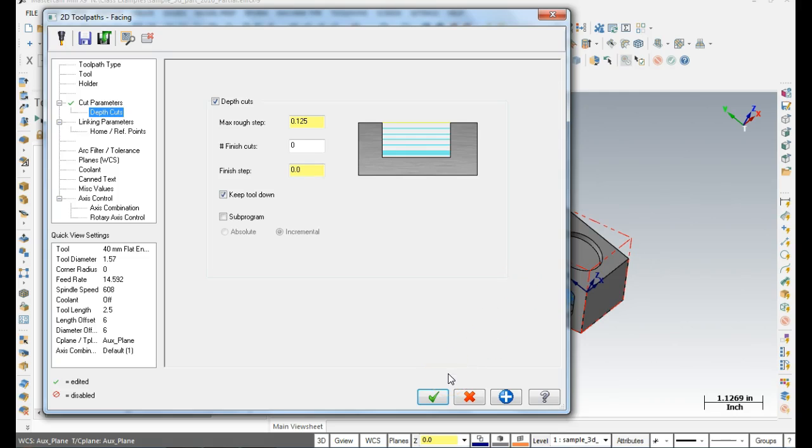Well, we have to have the face when we set it up, because we don't have a 5-axis machine. When we set it up, this face has to be lined up with the axis correctly. You're going to have to wedge it, because you've got a 3-axis tool, you're just going to come down and face it. Let's see how Mastercam handles it. So let's do depth cuts.